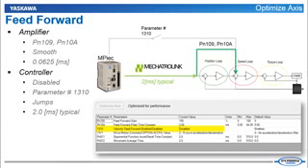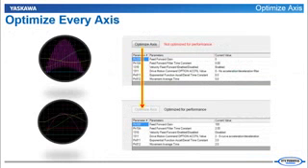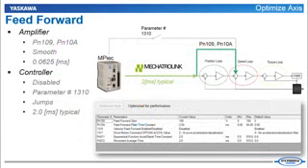After the servo is tuned for high performance, the response to the controller feed forward can result in many small jumps at every mechatronic cycle. Each jump produces a surge of motor torque, resulting in higher torque ripple and motor heating. Therefore, the controller feed forward is disabled.